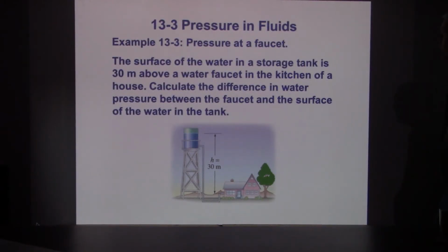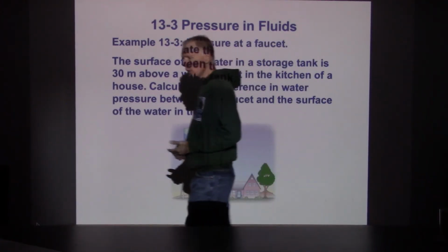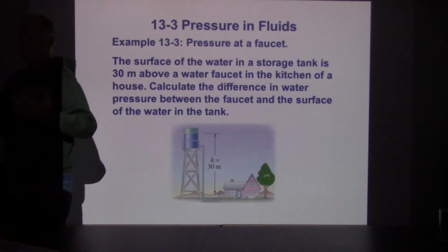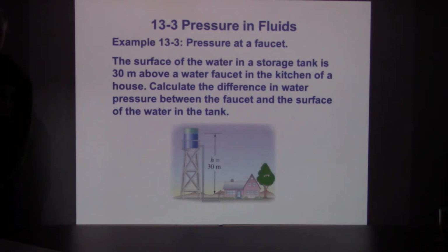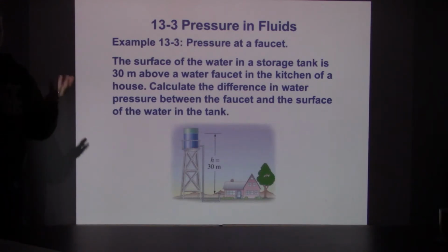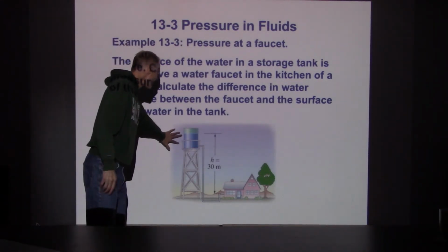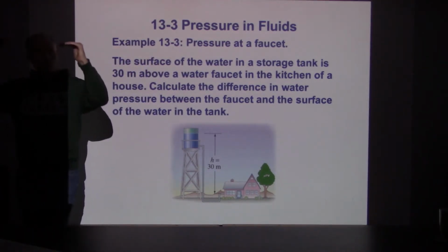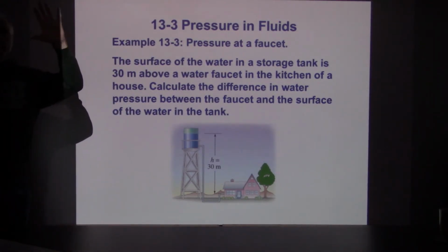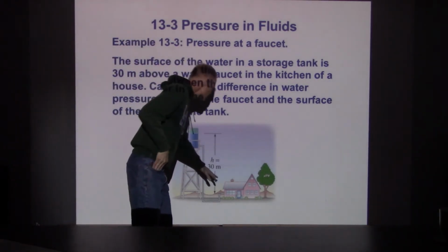Now 30 meters, that's a good tall tower. Here we don't see the towers because we just build the reservoirs up in the hills. So if you're wandering around up in the hills, driving around from time to time, you'll run into a reservoir of water, and that's how we maintain pressure. So you need the water stored at a higher elevation so that there's plenty of pressure for the users.